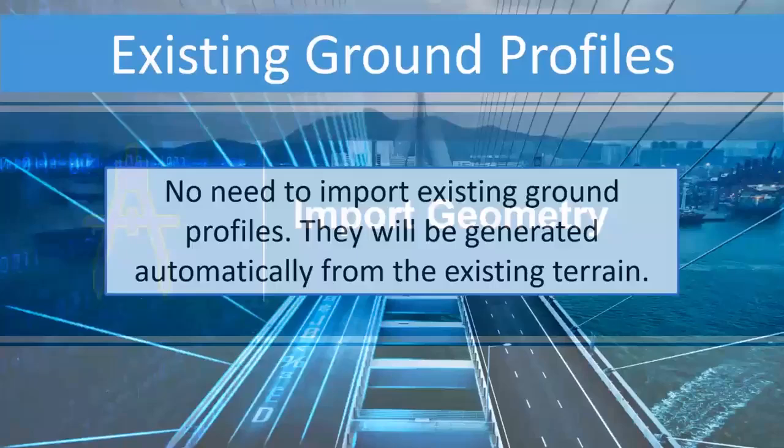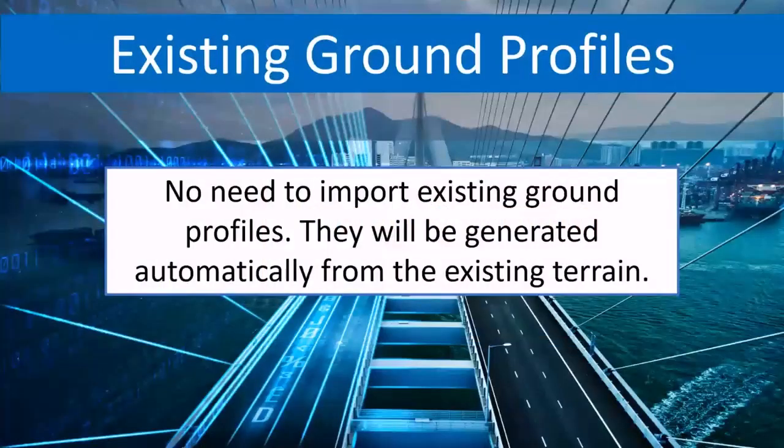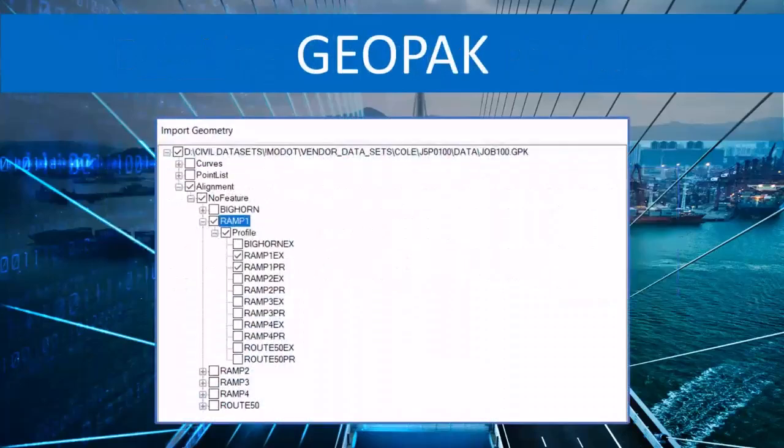Now, a couple of caveats coming in, for those of you that may not be familiar with OpenRoads, and you're going to be needing to bring some project data forward. The first one is this: you do not need to import your existing ground profiles. In ORD, the existing ground profiles are generated automatically from the terrain, so you do not need to worry about doing that.